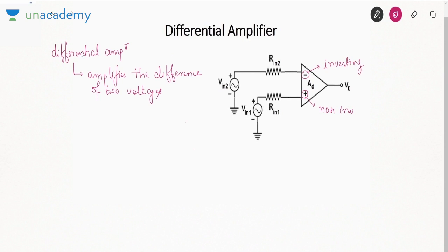So what I will assume is that there is no current at the input terminal. This you can almost always assume, no input current can always be assumed.